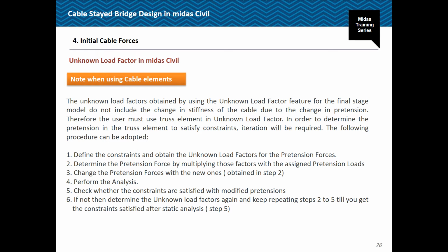Only in that case I will make sure that the stiffness is correct and the tension is accounted correctly, or at least the stiffness of the cable is accounted correctly. If the constraints are still not respected, I can run ULF another time and then repeat the same process. Update the newly found pretension forces, perform the analysis and check the constraints.